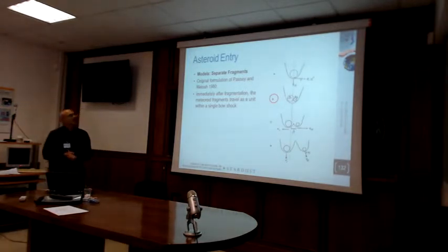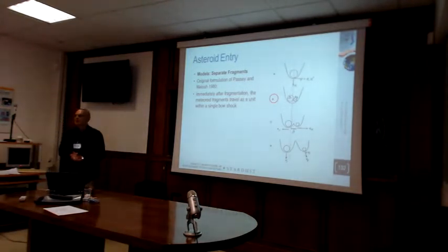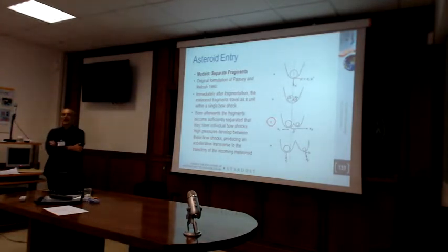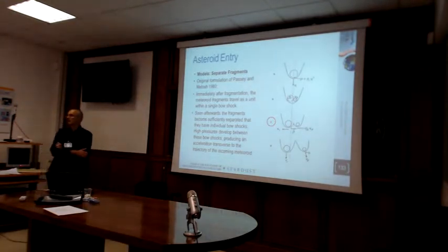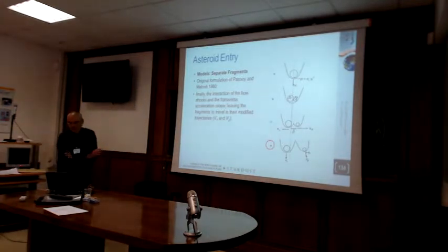So immediately after the fragmentation, both elements travel together, and they are basically confined in the same shock wave. Then, after a certain time, the fragments separate, and they are no more part of the same shock wave. There is an interaction of shock waves here, which gives further pressure to move the small object apart from the big one. And then at the end, there are no more interactions between the shock waves, and the fragments can be considered independently flying.